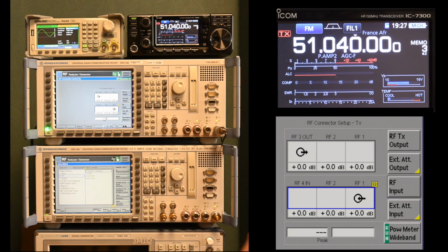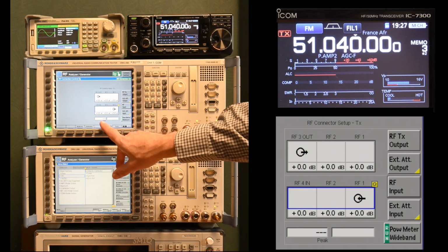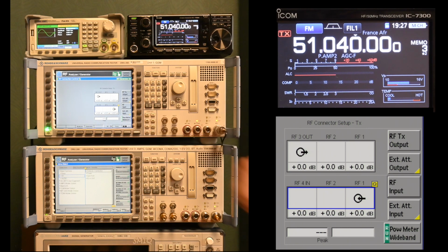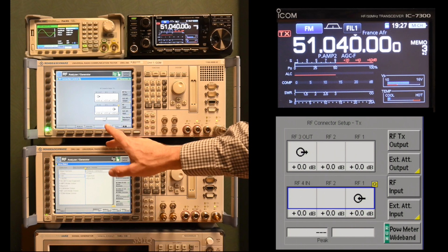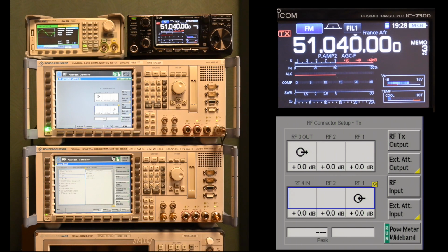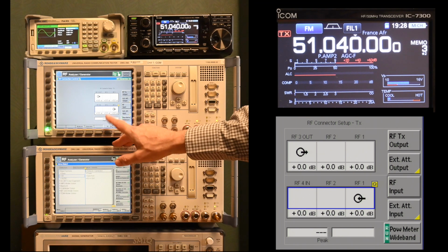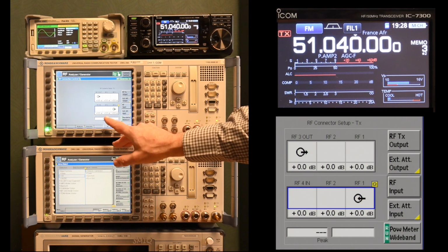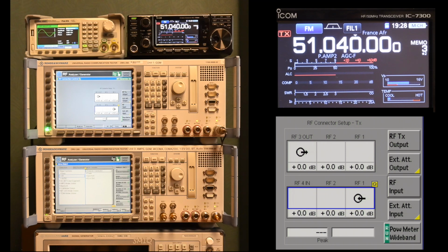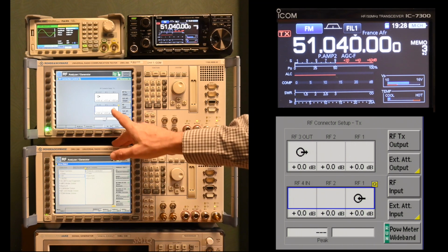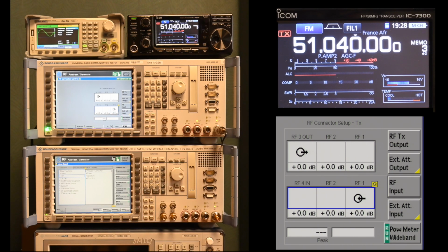Now I'm going to do the wideband power measurement, and it is shown right here already in the connection screen. It's also shown on another screen, for the wideband power analyzer, but it's also shown here. I think the reason is that they want you to be able to see the power level right away in this menu, whether a signal is present, whether it will be overloading the unit, and whether there's any reason to use attenuation settings or otherwise, which is fine.